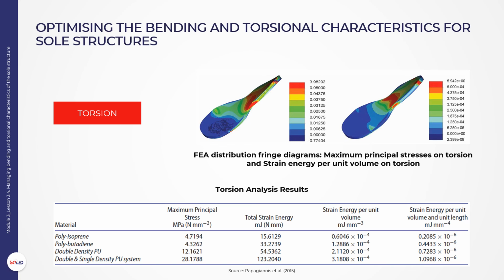The table presents the results of the analysis for the 4 material combinations selected. High values for principal stresses are due to boundary conditions that force Cartesian translation of points rather than rotational movement, Figure 9. Calculated values for both maximum principal stress and strain energy are higher for increased Young's modulus of the sole material, indicating a realistic approach to assessing torsion deformation characteristics of footwear components. According to the results of the analysis presented in the table, it is concluded that the soles are very flexible.